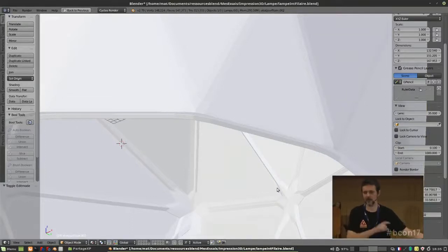And the other thing is that if you import the 3ds file directly in your project in Revit, when you cut it with the cut tool, you don't see the hatches and things like that. So you have to import your 3ds export from Blender in a family, and then you place your family in your project, so that when you change your file in Blender, you import it again in your family, and Revit will update it automatically. So with that workflow, you have almost a back and forth possibility.